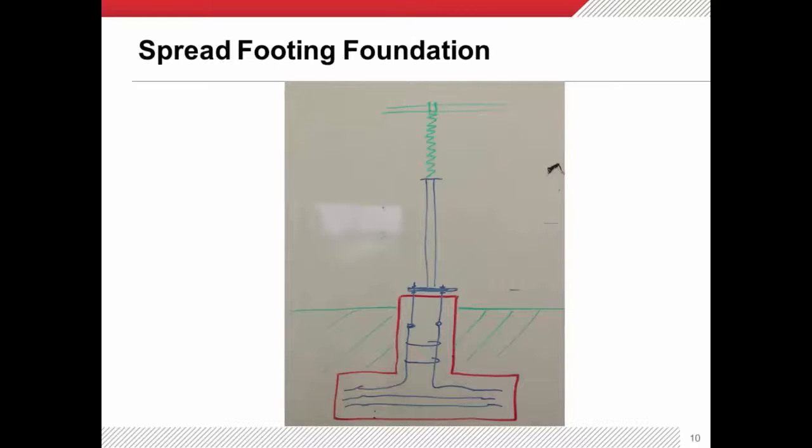You don't have to go nearly as deep with this. And unfortunately, I don't have a drawing. I couldn't find one today that shows this. But you may only have to go down 3 or 4 feet, and so you dig a big hole. You frame it up with wood, and then put your rebar cage in, and then you're going to pour the thing. I've never watched them do this. I've always assumed to get that neck part on the top is a second pour. Anyway, works like a charm. Takes a lot more manpower to do this.